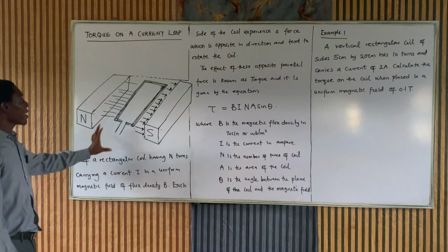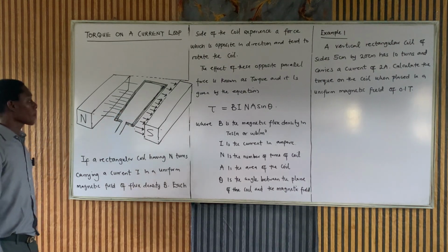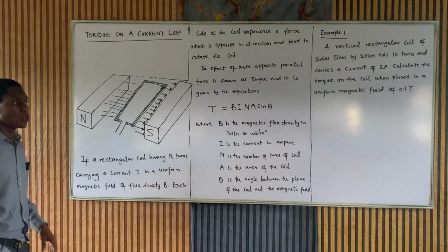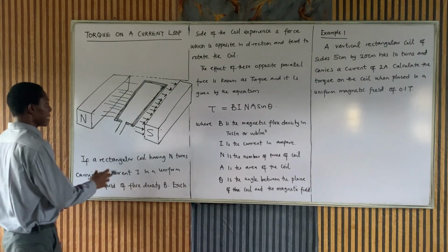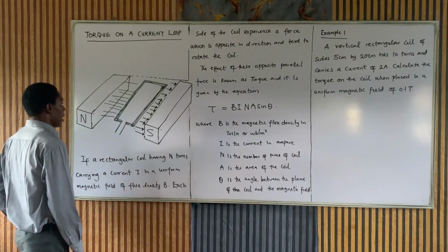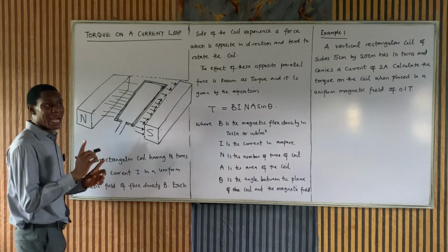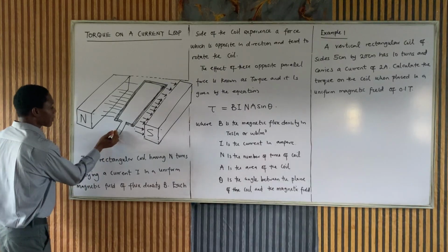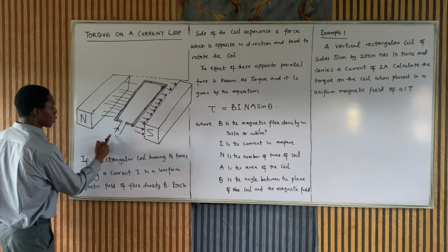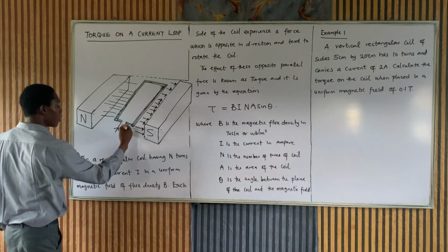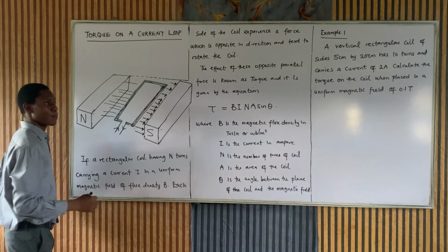You see, if we have a rectangular coil as shown, and current flows through this coil, and this coil is in a magnetic field, then there will be motion on this coil. And let's analyze why the motion would occur. Now understand that, let me assume that current flows inside this conductor inward like this and goes like this. So the current here comes outward this way.